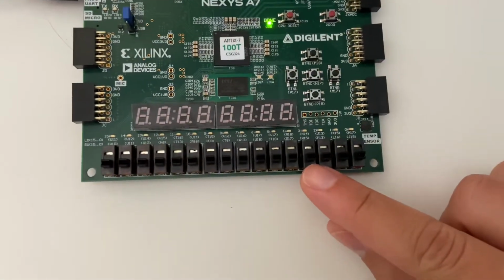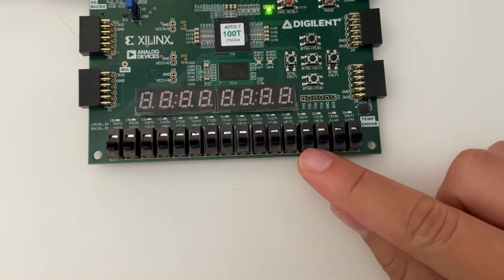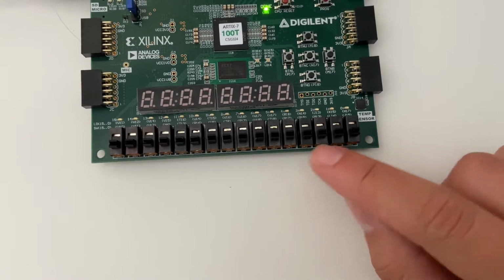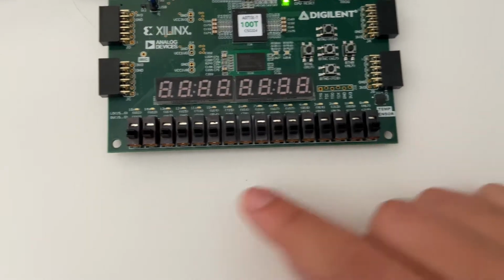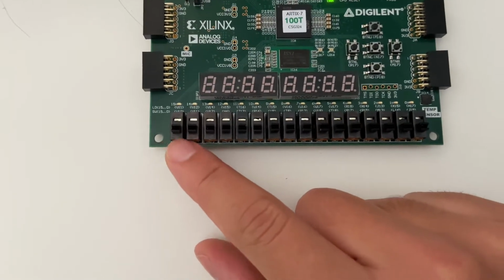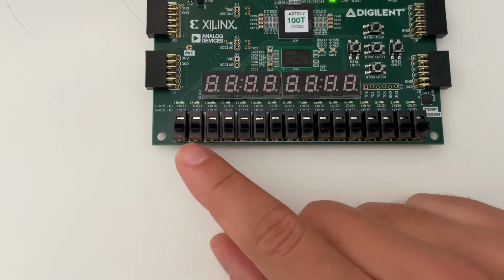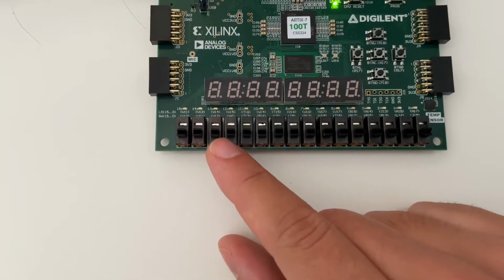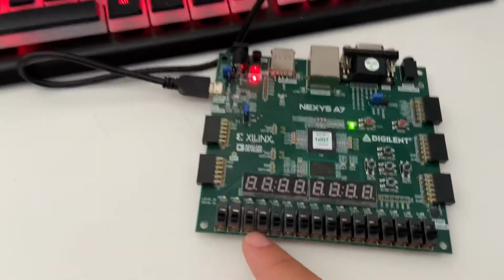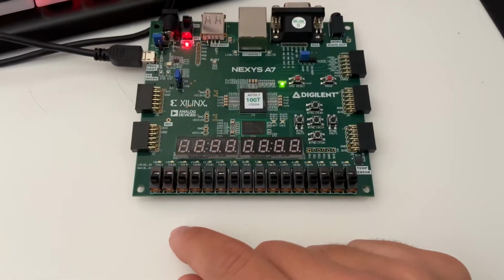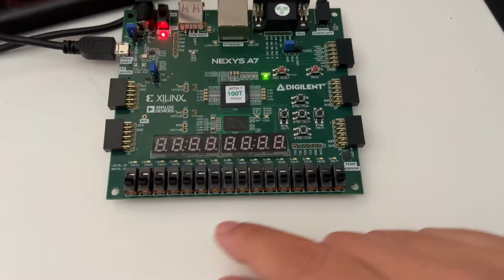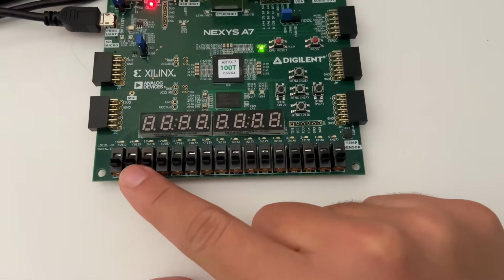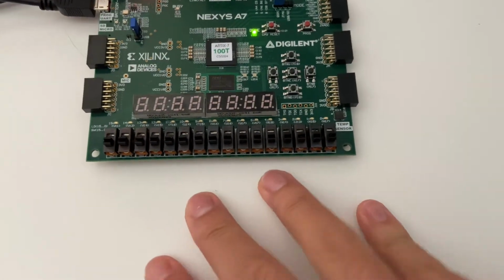We can see these 4 switches right here represent a 4-bit input, which we'll call M, and that represents the on time of the square wave. And then we have these 4 switches right here, which represent the 4-bit number N, which represents the amount of time off. Based on the constraints of this lab, we'll have M times 100 nanoseconds and N times 100 nanoseconds. And that's what we should expect of the output.